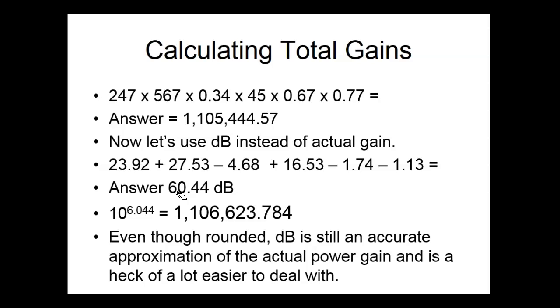So when you get into systems, this cable right here can have a maximum of 3 dB drop over 100 feet. Now to you that don't mean much, but I understand that. I know it's 70.7%. I know that, right? Because I understand dB. So minus 3 dB, that's what we call the cutoff point of just about every medium.